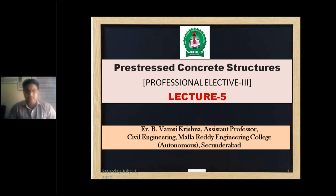And again, based on the application of the load, pre-stressing was classified into 3 categories. One is uni-axial pre-stressing. The best example for uni-axial pre-stressing is beams, right? And biaxial pre-stressing: we do biaxial pre-stressing for slabs.